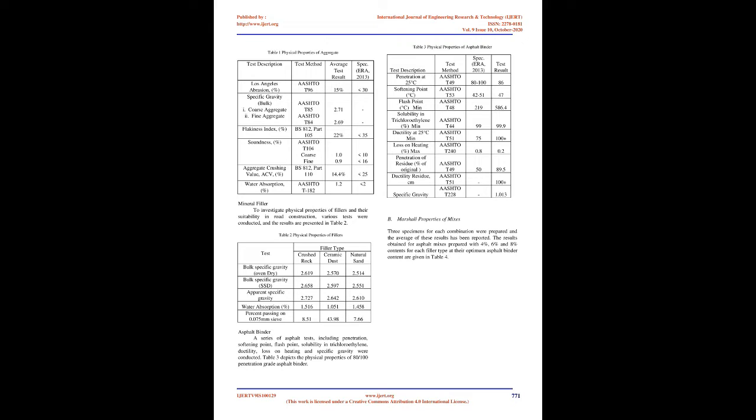23. Studied the performance changes and fundamental material characteristics associated with moisture damage due to various anti-stripping additives in hot mix asphalt, HMA, through various experimental approaches and a numerical solution. Moisture susceptibility evaluation of asphalt mixes was conducted using two alternative additives, fly ash and cement, and hydrated lime as control mix. The test results showed that all mixes performed with good resistance to moisture-induced damage.